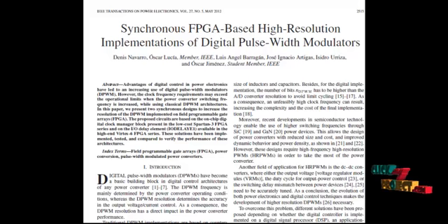Almost every FPGA includes a DLL block with phase shifting features. Taking advantage of these resources, the proposed architecture attains excellent conditions. The proposed DPWM is in principle independent of FPGA implementation, but an integrated circuit implementation would need the development of a DLL with phase shifting capability, which is the most complex part of the architecture.